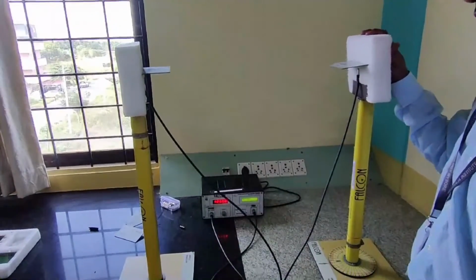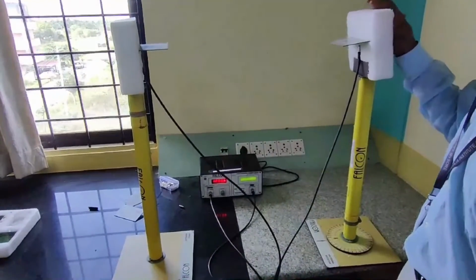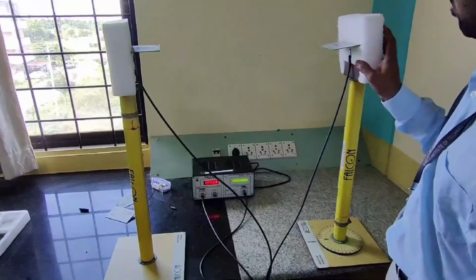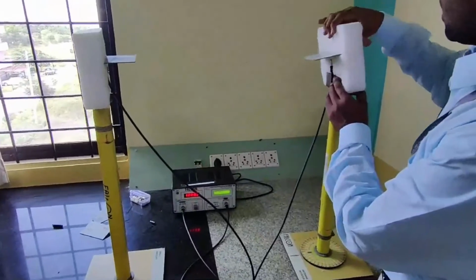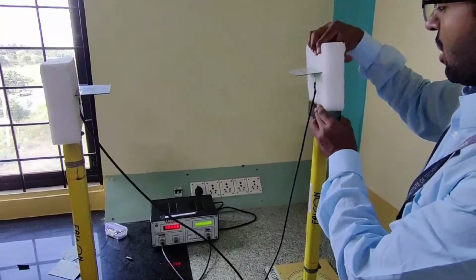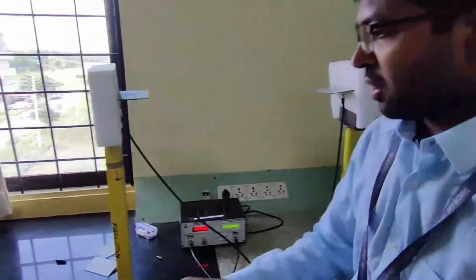This arrangement is for electric field measurement, or the theta E measurement of the beam width. Now if you want to measure theta H, then the arrangement should be like this, or using the other bend which is here.